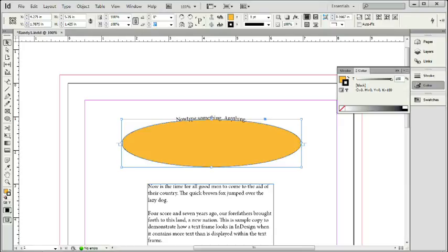One last concept before we finish this lesson. With your selection tool, click on absolutely nothing off the edge of the page. Then press Command or Control-A, depending on what platform you're on. When you do that, with most any tool but the Type tool, that command selects every element on the page area and its surrounding clipboard.